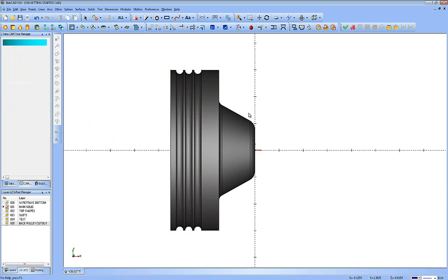Now what we want for the toolpathing is the profile, or the wireframe lines and arcs profile of the part to toolpath off of. So to do this, it's very easy. This procedure will work for any solid that you create or bring in to BobCAD for pulling the profile off in lines and arcs. We're not going to use the extract edges feature because that will just give us the rings of the surfaces where we want an actual slice through the model.